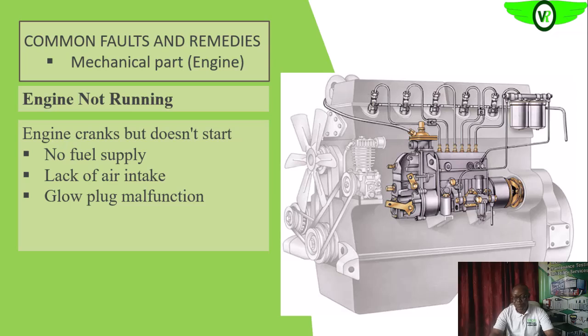So if those plugs are faulty, what it means is that even if you put it on, those cylinders will not be heated. So you have trouble starting or initiating the combustion process. So injector issues, as we said earlier, when you have issues with the pump not delivering the right pressure, then the nozzles too. It is possible that the nozzles have gone out of calibration.